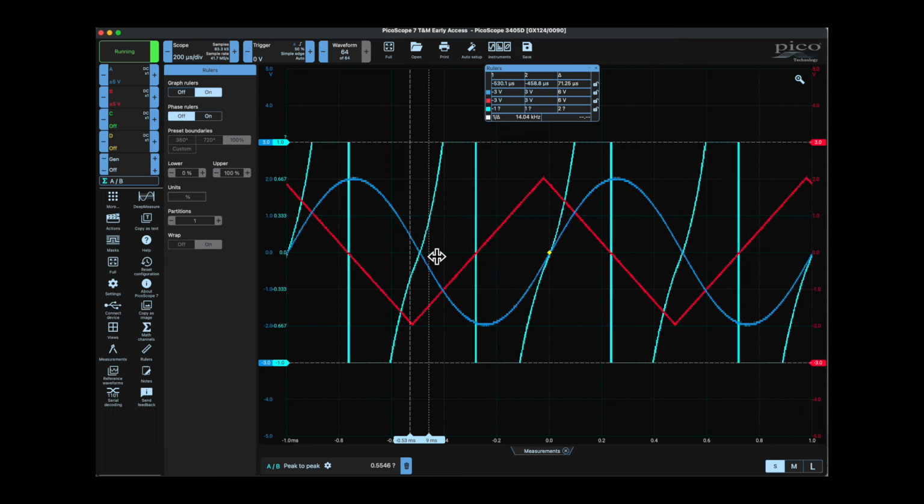So here we see that the peak is 0.5 between the two rulers that I selected, and again it's dimensionless. Well, this is okay. It still accepts the negative peak. Yeah, no, and at the positive peak it goes wrong. It's not able to measure anymore. So it's not dealing very well with division by zero issues. That might be a concern depending on the type of measurements that you want to make.